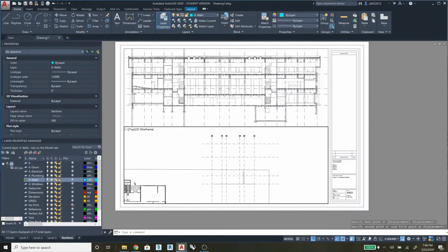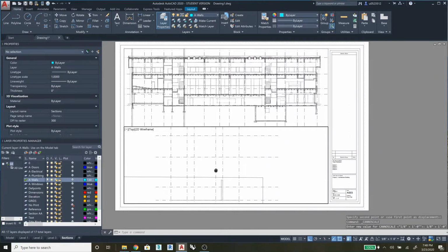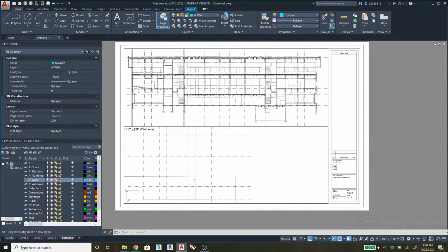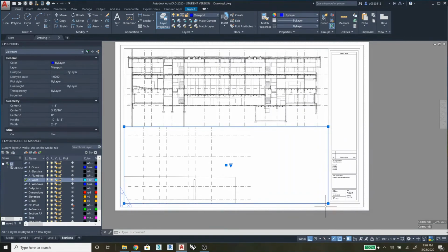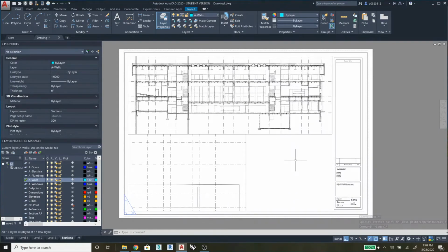Okay, so we'll go back to 1/8 inch scale, and it should be able to fit when all is said and done, because it's going to be the same scale as this one above, so it should be able to fit on this page just fine. Now if I wanted, I could also change this viewport size. I could have some schedules or legends out here that don't have to be in this viewport that could give more information on this page.